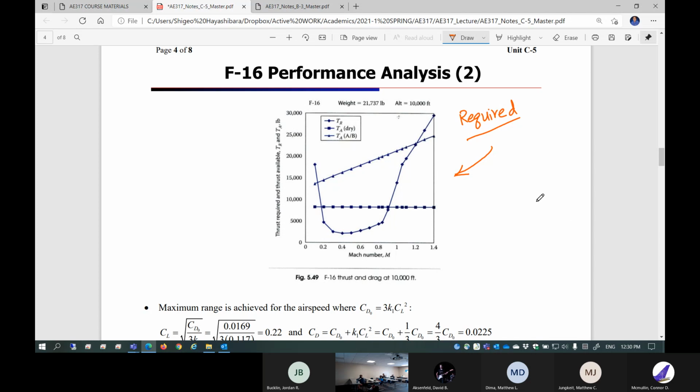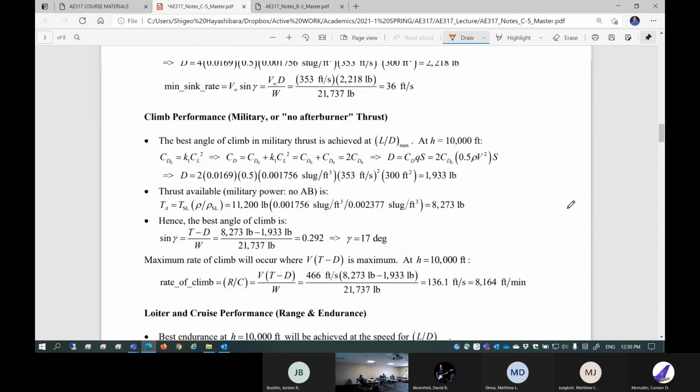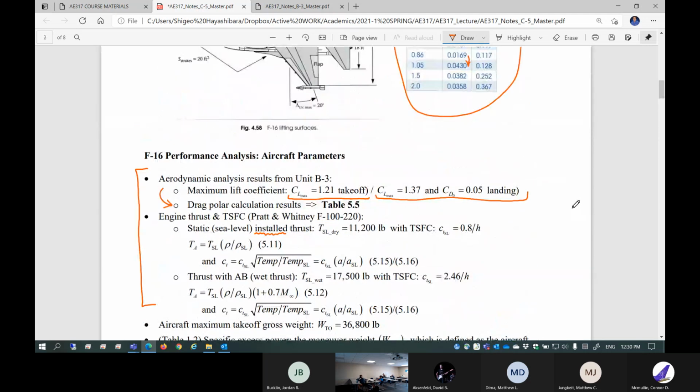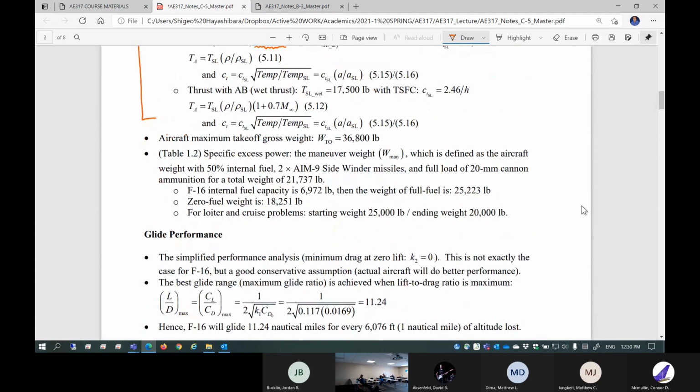Okay. So anyways, this is absolutely required out of that information here. The next thing is, of course, you have to figure out how much total weight for takeoff configuration. So payload is important. Of course, SAE team, you guys have payload. And then what kind of materials you're going to choose now comes into play. Okay, so your airplane's design is getting closer and closer to something you really want to manufacture. So this is going to determine takeoff gross weight.